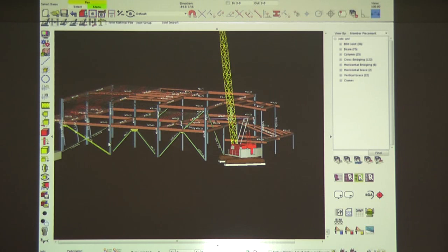this column in SDS2 and in Revit. So the only link between the two is an ID number. It's a license plate number. It's a serial plate. It's a serial number. This one has a very specific number to it. Well, I pass that very specific number off to Vulcraft in Norfolk. They design a joist that's going to be sitting on top of this, and when they return it back to me, I know where to position the joist in the model because they sent that number to me and I said, position relative to this column, I'm 2 foot to the left, draw the joist here. So GUIDs are very important in the interoperability world.